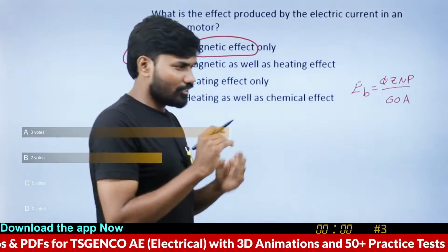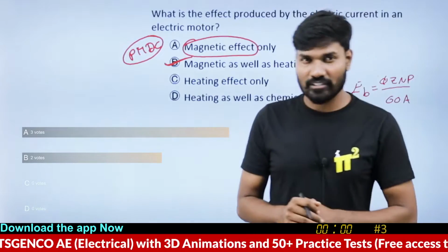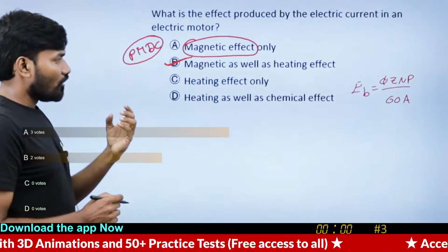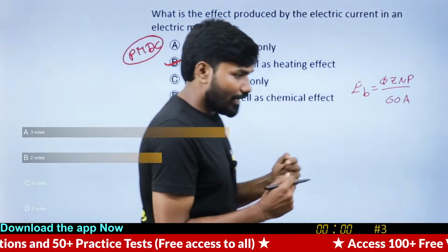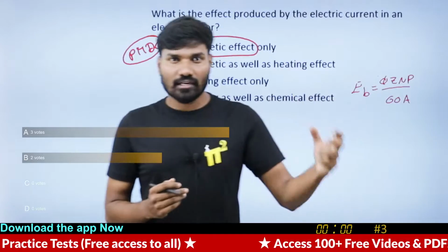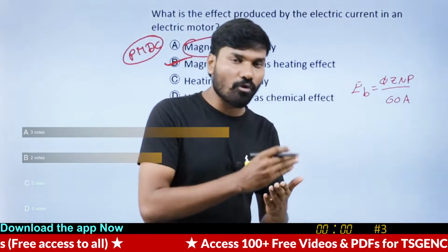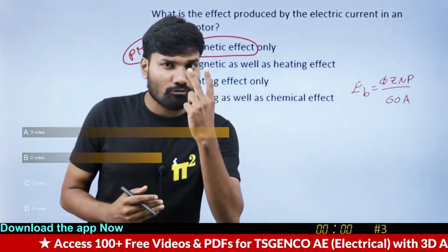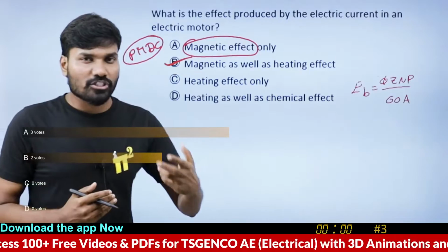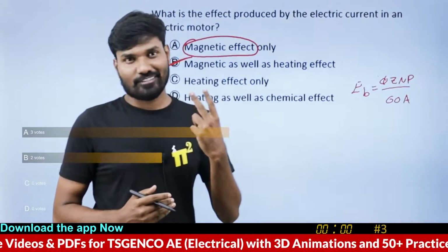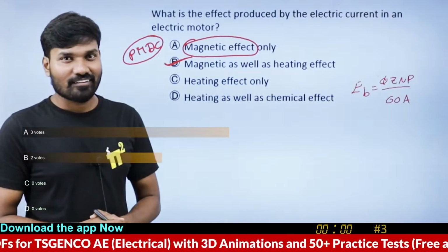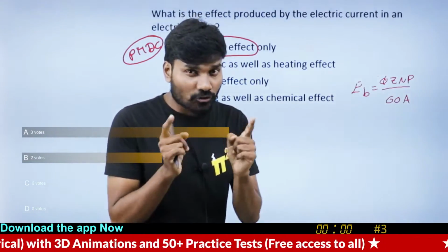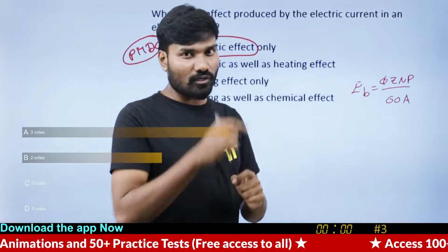See here, one thing. You guys are giving mixed answers. Let me put it this way. Key point, guys. Remember this. To have electromagnetic Faraday's law work there, to get a Lorentz force there, you need two fluxes. To generate EMF, you need two fluxes. One flux is not enough. Two fluxes are required. Interaction of both the fluxes will give you the torque.